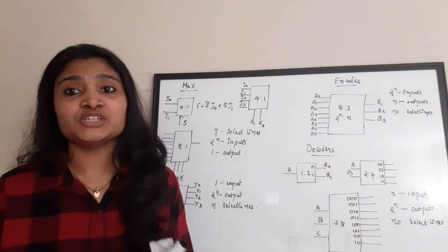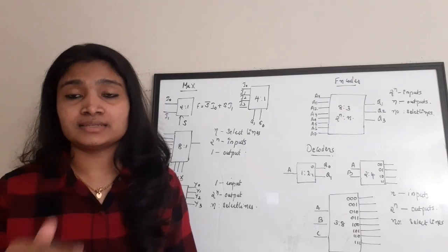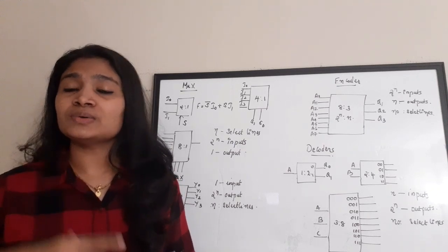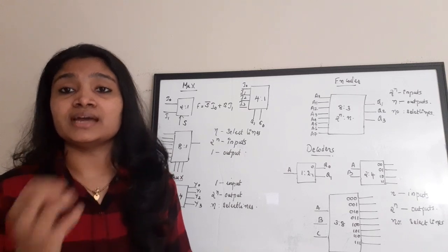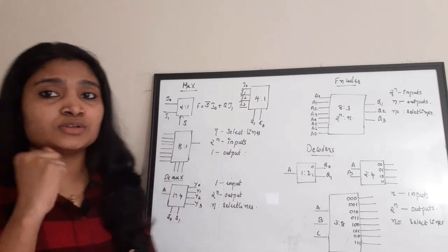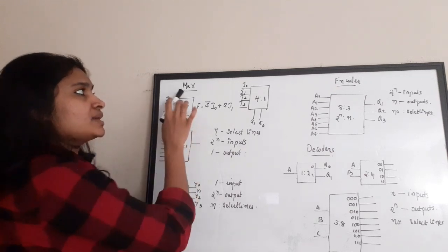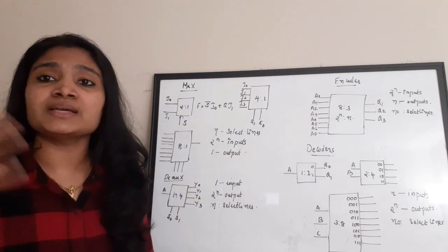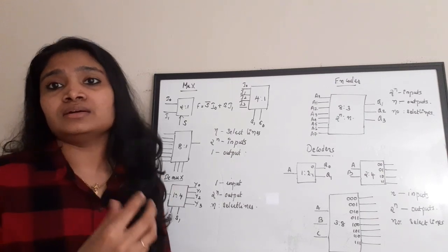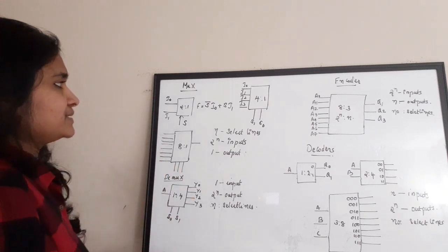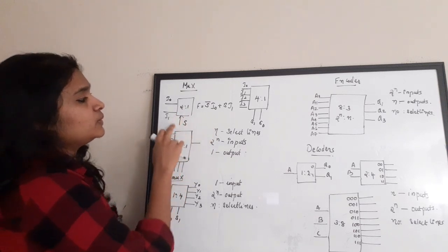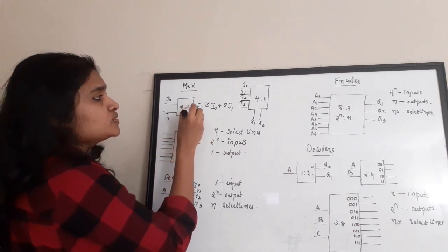Okay. The next topic that we are going to discuss is mux, demux, encoder and decoder. We will see how these work, what the number of inputs and outputs is, and what the number of select lines is. Okay, so if you are talking about mux, mux means multiplexer. What it is doing is, it is generally going to combine inputs; we generally call it multiplexing. Or you can say that according to the particular select line, it is going to produce an output.